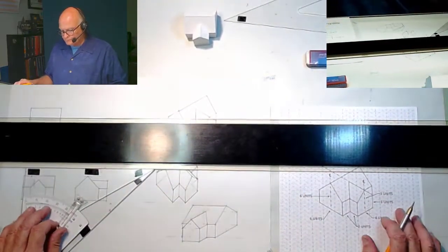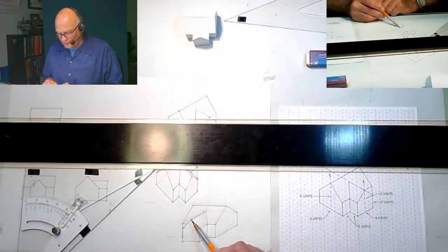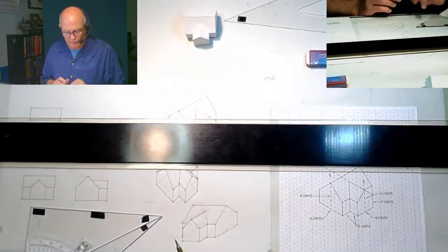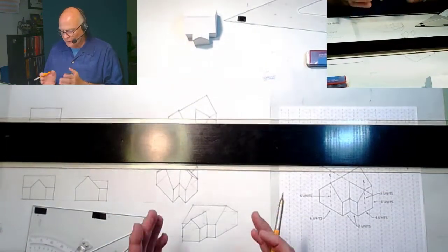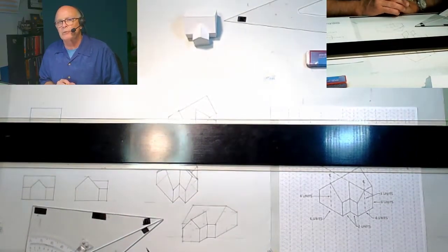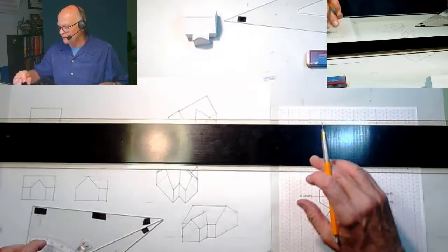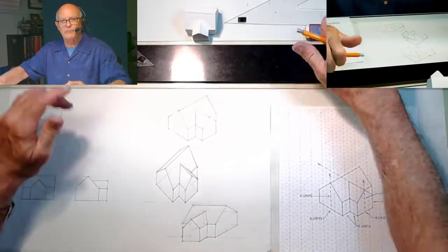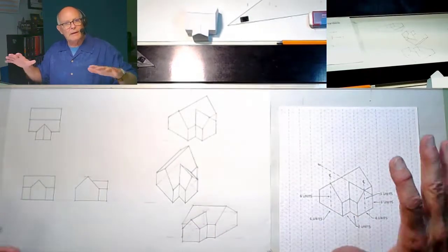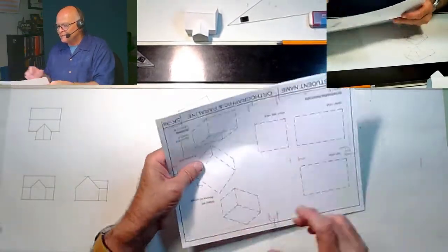Okay, so that is the completed elevation oblique. The length of this was found by actually just taking the dimension right off the side elevation because that's the distance left. We could go through a lot of different ways of proving that, but for expediency purposes, I think that's the easiest way to solve that element of this drawing. So as before, you're going to need to complete the drawing and then rearrange this on a final drawing in such a way that it follows similar to this.